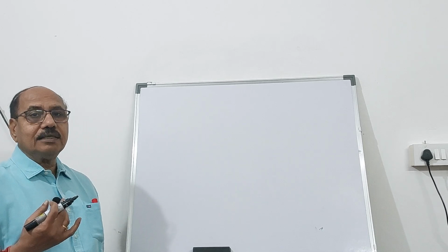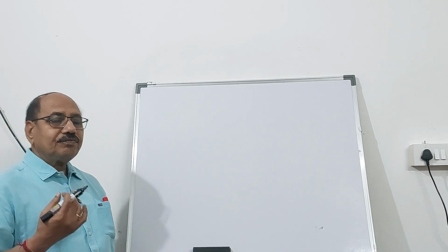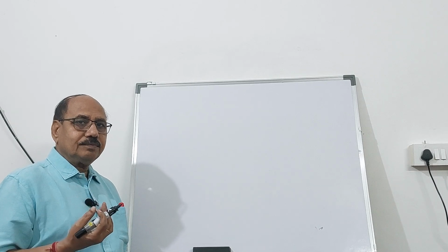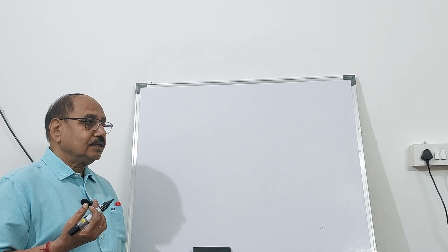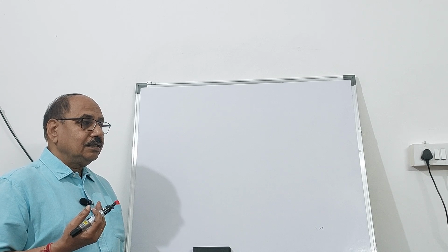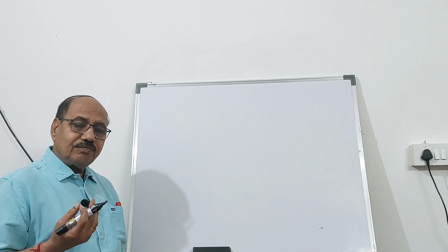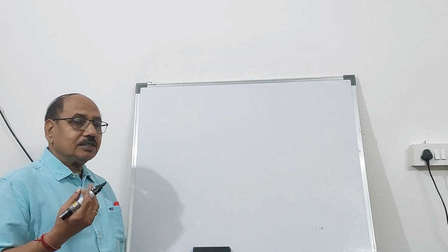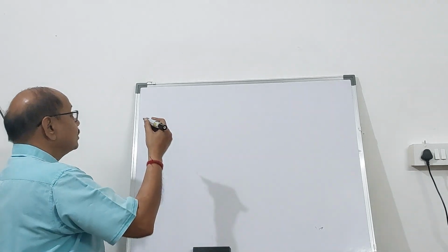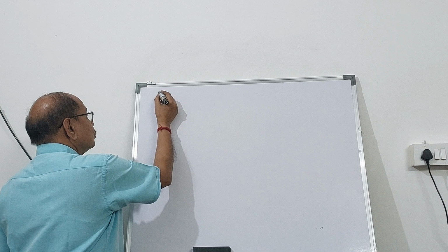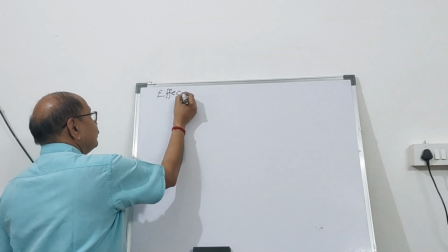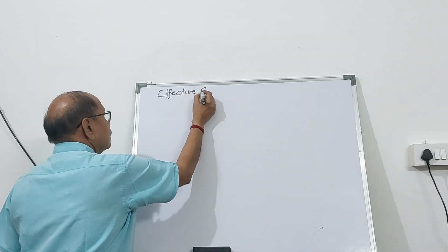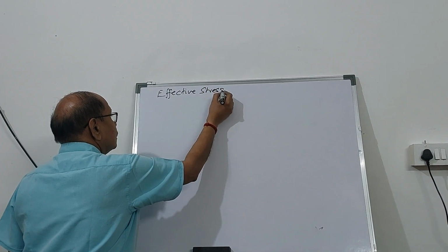because the strength of the soil mass is a function of effective pressure and not the total pressure. And the settlement is also a function of effective pressure. So it is very important to know the effective stress value.